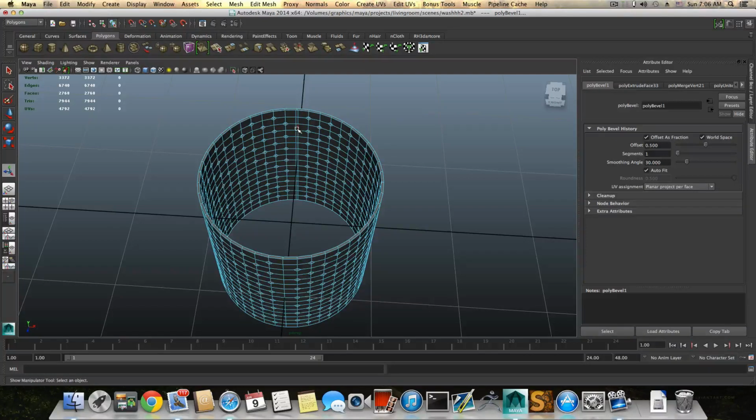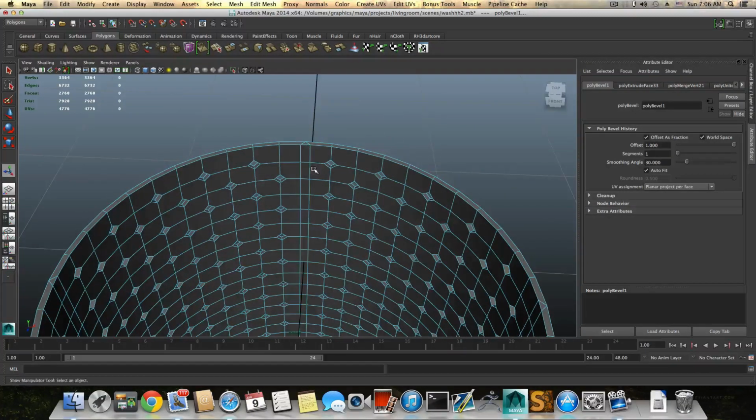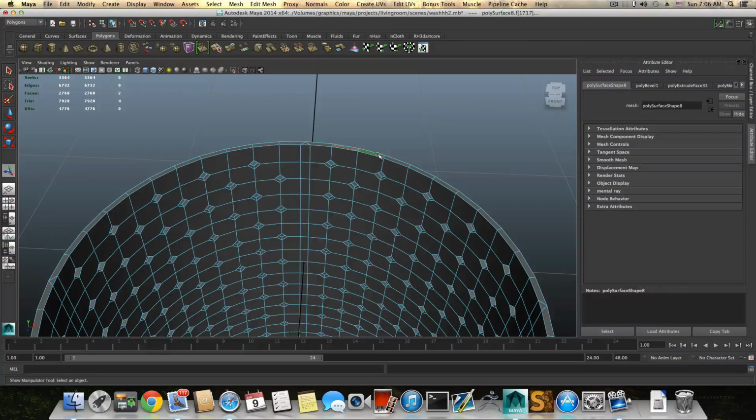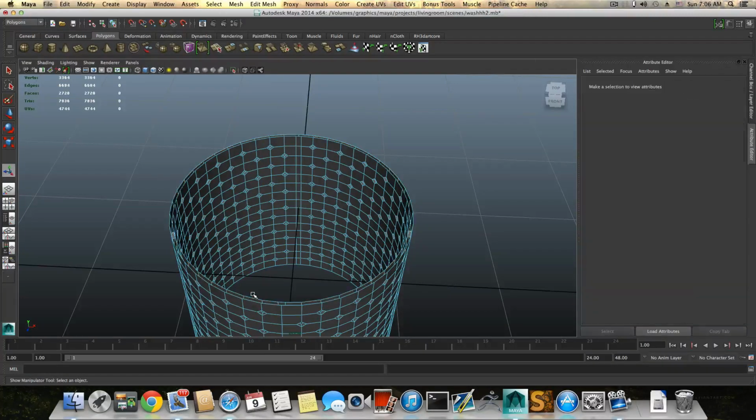And we can change the offset, so it will open a little bit that way, and then let's choose all those faces here. Shift select this, double click this one, and select these, double click. Do the same here and do the same here, and press delete to delete this.